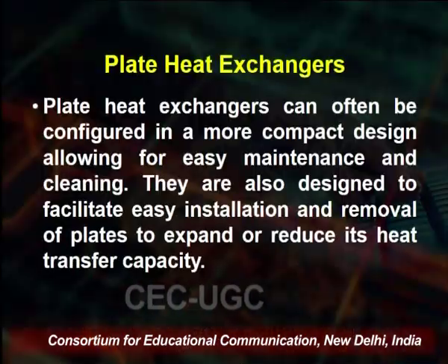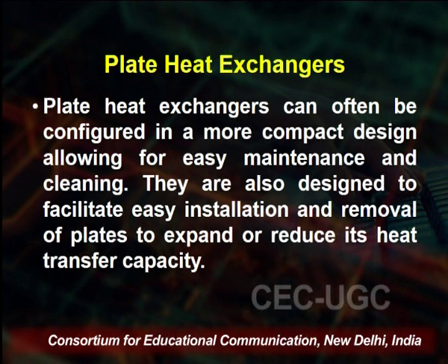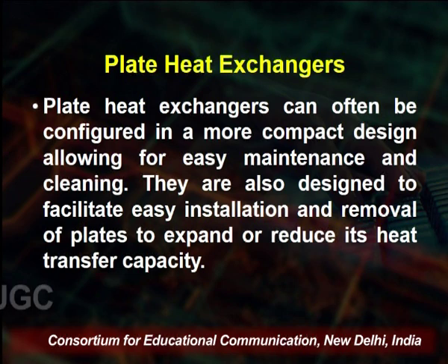Plate heat exchangers can often be configured in a more compact design, allowing for easy maintenance and cleaning and to fit in particular devices. They are also designed to facilitate easy installation and removal of the plates to expand or reduce the heat transfer capacity.